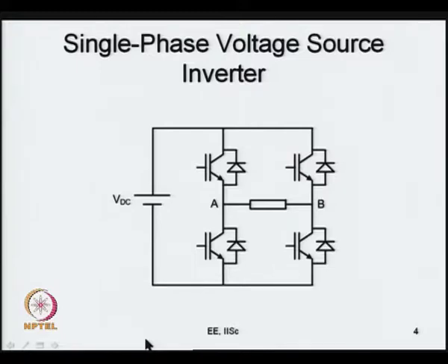All right. So, in the case of the so called bipolar PWM, what we do is we keep these 2 on and the other diagonally opposite switches off. That would apply VDC with a particular polarity. In the other way, the other diagonally opposite switches are kept on and the other 2 are off. That applies minus VDC.